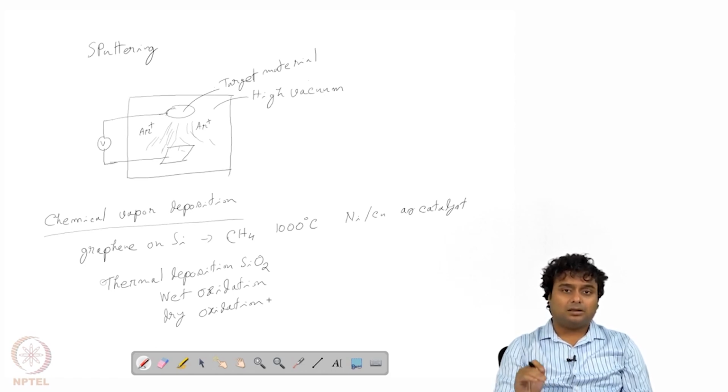So the surface will be much better and suitable for device application, and the whole oxide film can be deposited in much smaller time. Rather than that, if you had chosen dry oxidation for the whole 1 micron, then it would have taken a lot more time.